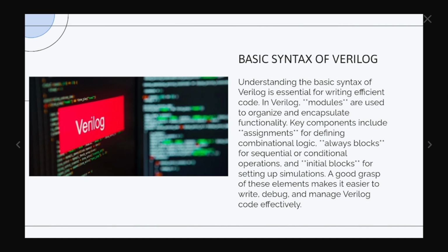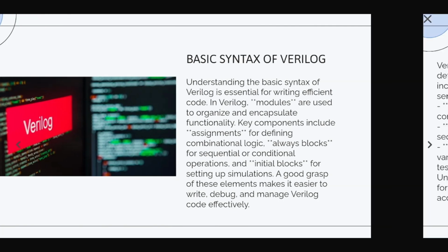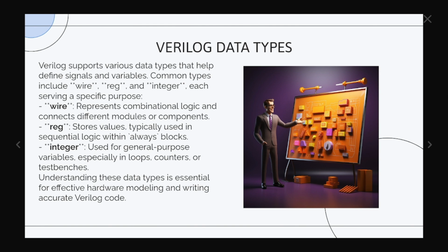Next is assignments, which we use in combinational logic. The basic assignment is given by the assign component. Always blocks, which we use for sequential or conditional operations. Initial block for setting up simulations. Next is Verilog data types.